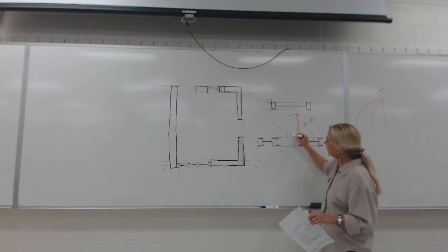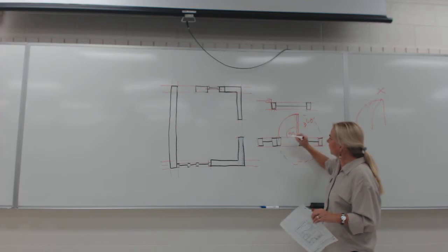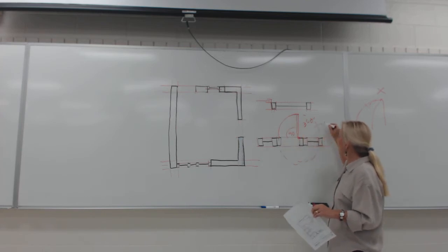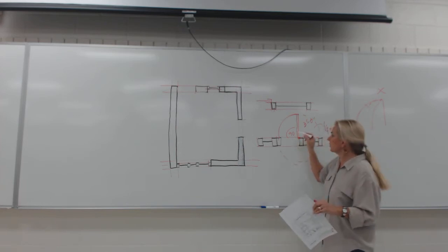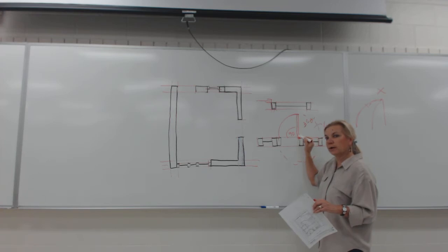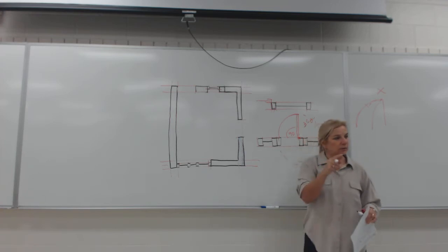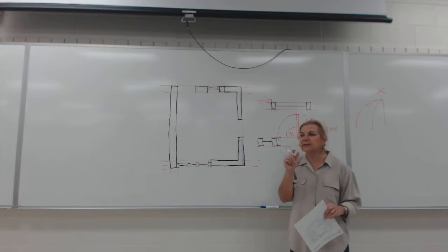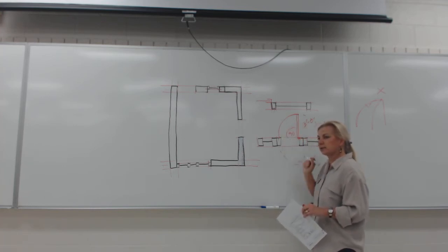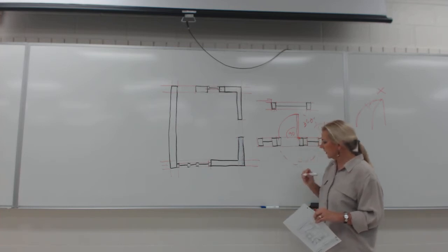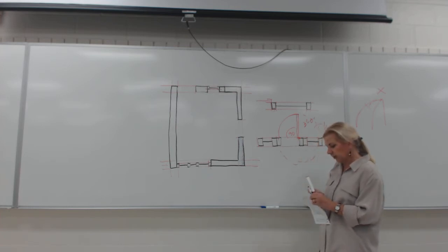So what we need here is 90 degrees and perfect quarter, so 1/4 of an arc. For this, the best thing to do is to construct the 3-foot door and then get my or your circle template and find the circle and place the circle so the center is here, and then just find the arc that fits perfectly. If you can't find an arc that fits perfectly, I'll show you a little trick.